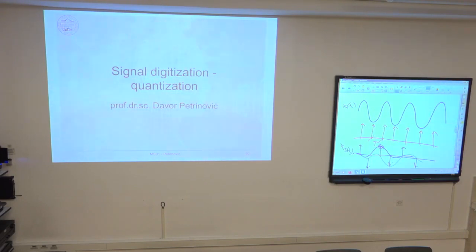So this internal hardware of this AD converter must operate at 250 times higher frequency than the final sampling rate at the output of this AD converter. And it is okay for the audio range, where you have 44.1 or 48 kilohertz. It is a few megahertz, a few mega samples. You can design such a circuit. But it is a big problem if you want to design this kind of architecture for some radio signals, where the final output sampling rate is some gigahertz, let's say. Then you cannot use this kind of structure.